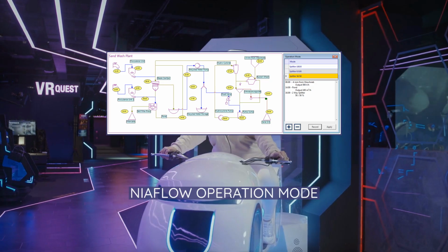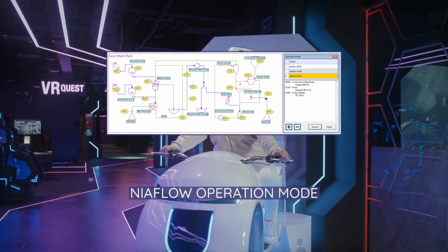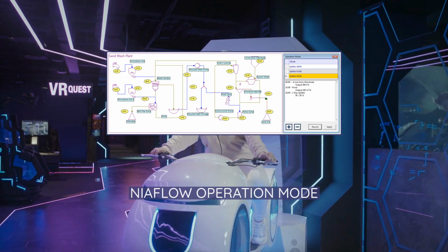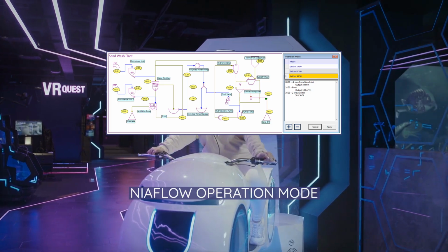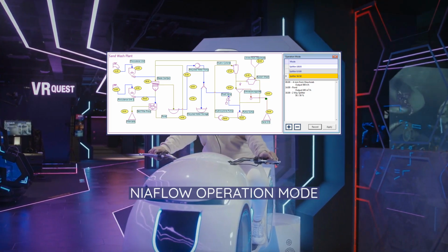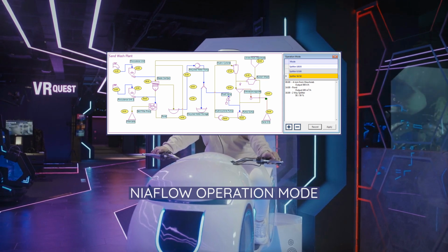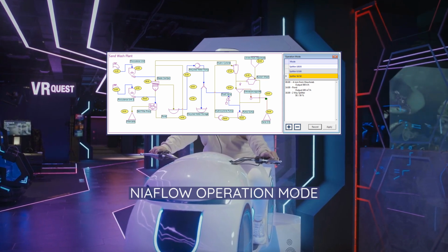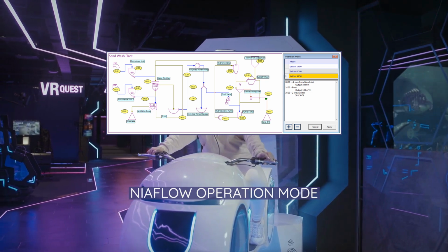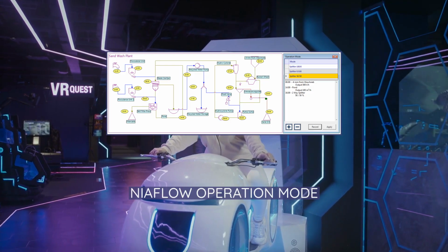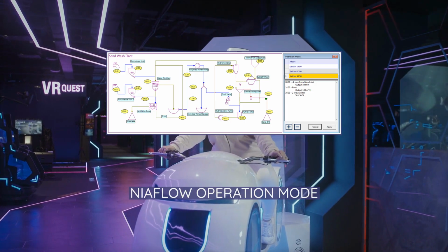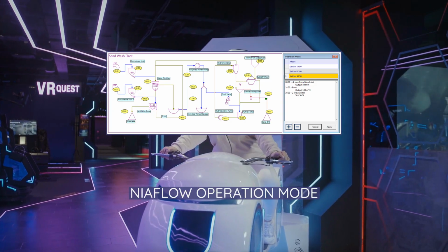Material handling and object calculation. Most objects in NIAflow are connected by lines where each line represents a material transported from one object to another. Any number of incoming lines can be attached to an endpoint of an object. During calculation, all incoming materials are blended into a new material. Calculations are dependent on the type of object. At the conclusion of object calculation, the resulting material products are connected to the outpoints of the object.